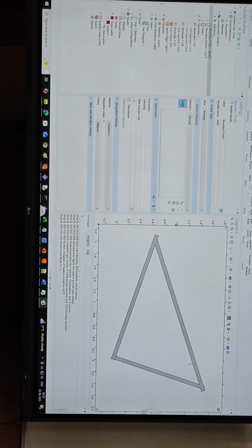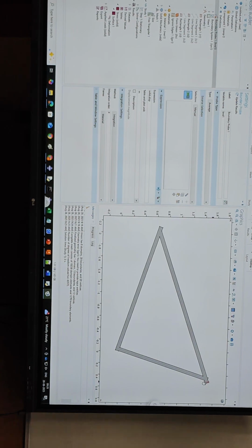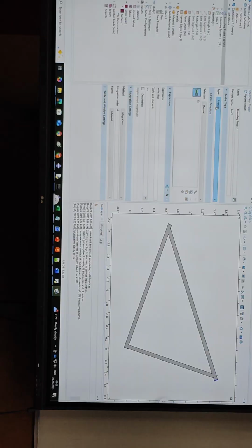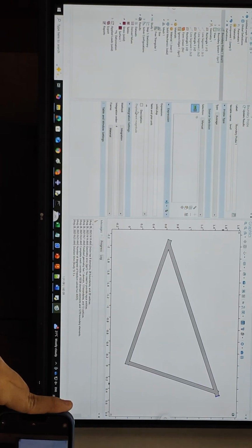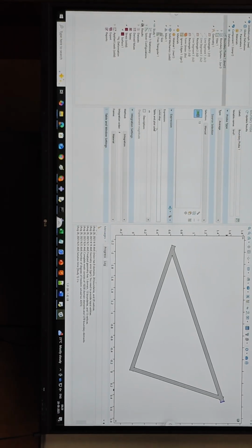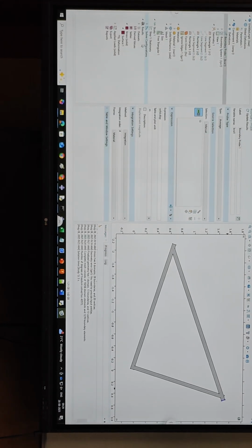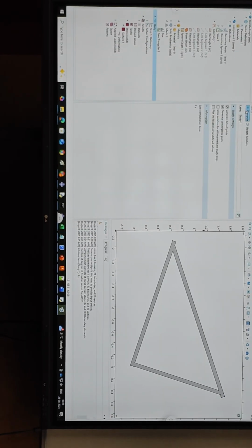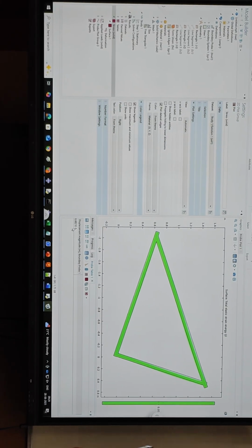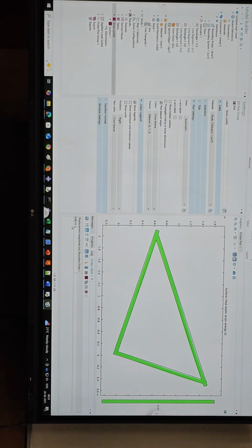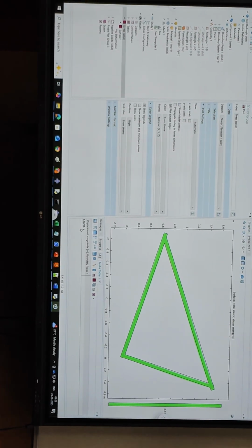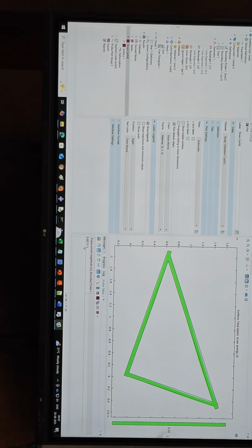And I'll go to the boundary where I gave that load over here. Right? So I'll have to click that. Now once that's selected, I want the average of the values of displacements there. This will be the magnitude. You can also give u, v, w and take the components. Now if I run it again, keeping this probe, you will get in your table the corresponding displacement value there, the displacement magnitude. This way, even if you're doing a displacement control and want the reaction force, the same process is involved. Probe it, ask for the reaction force, give the displacement, and you'll get the corresponding force.